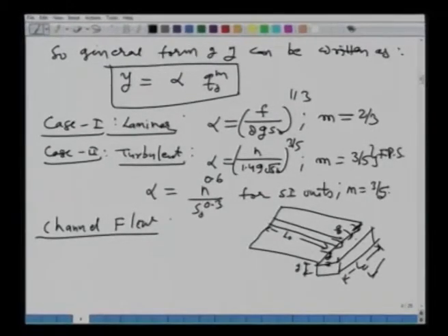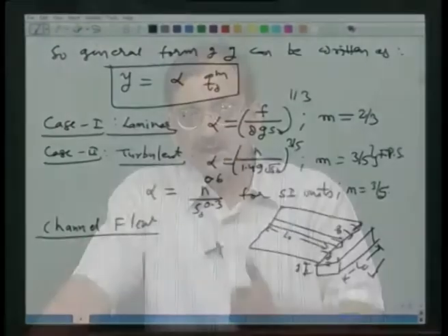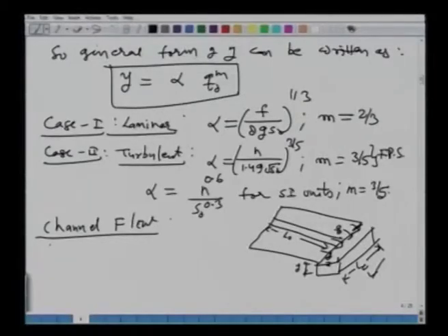Okay. So, now our objective is to determine what will be the flow depth and velocity in the channel given the discharge in this channel. Okay. How can we do that? How can we determine the flow depth and velocity in a channel? Well, we use the famous Manning's equation. All right. We would see that this problem will not be very straightforward. All right. It will involve a little mathematical jugglery. All right. So, let us look at that. First, define various variables involved. So, you have LC is the length of the channel.